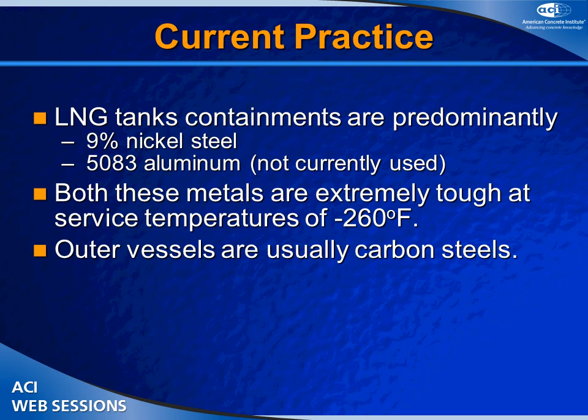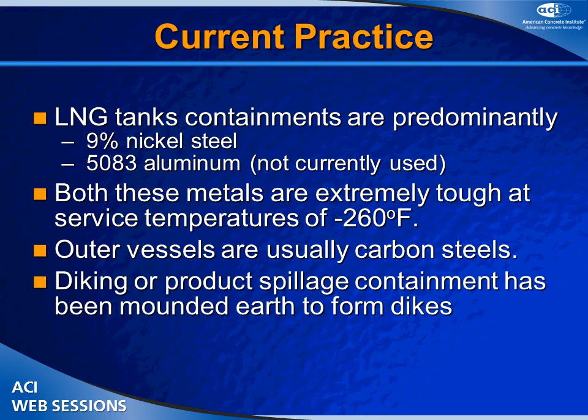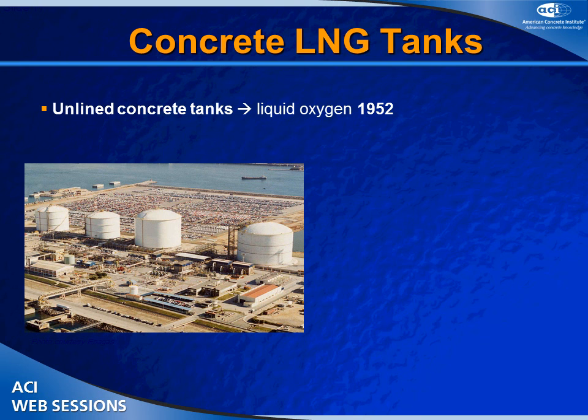And the diking or product spillage, I talked before about the berms. There have been earthen berms, or there have been concrete berms, pre-stressed concrete proposed for containment. To give you an idea of the history of concrete in LNG, I mentioned the first was 1953, but there was actually a tank in 1952, kind of a test tank. Precast concrete tanks, these are predominantly the Preload design.